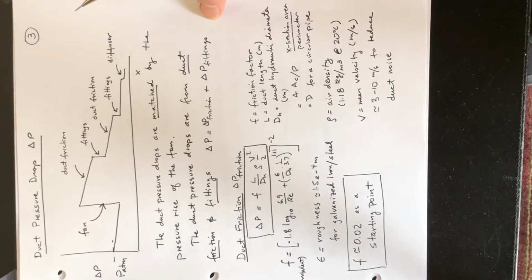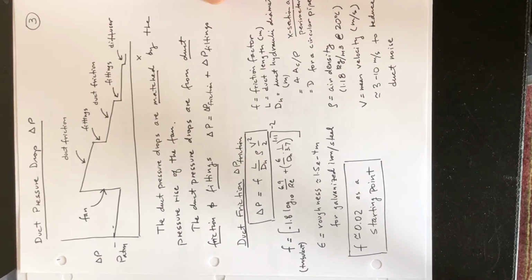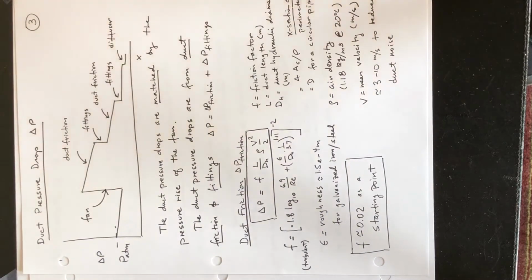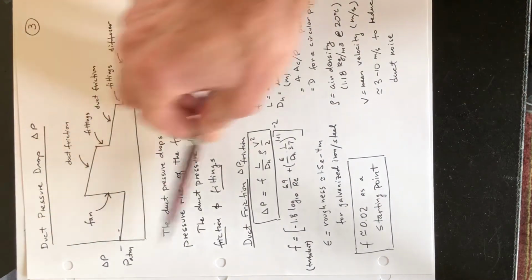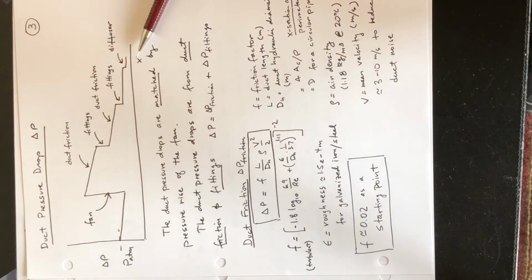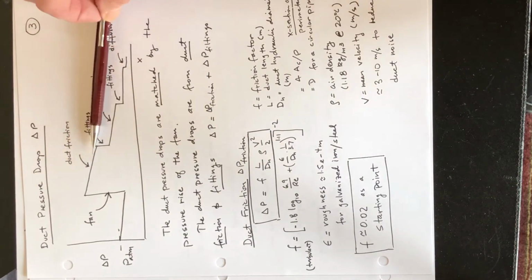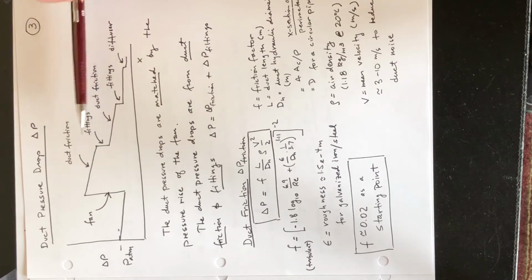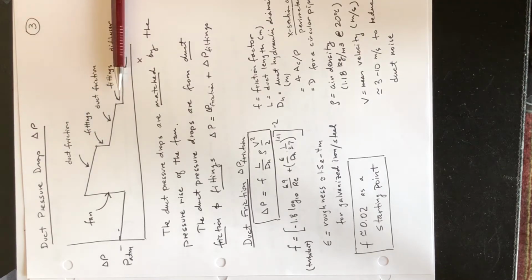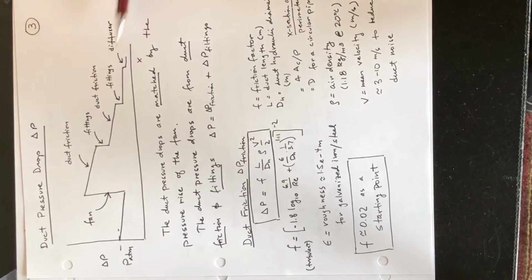So now let's go ahead and take a closer look at the zone pressure drop. We put this graph down at the beginning of class earlier in January, where we have pressure drops due to the duct friction, linear with length, and then any of the fittings that are there will create a pressure drop as well.